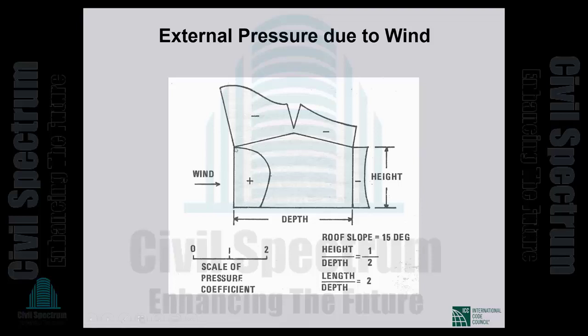And you see very clearly that with a gable roof, the suction here is the highest of any point on the surface of the building. This is a very basic problem in wind design. Because of that very high suction, the windward roof may be sucked up. Wind may suck it up, and when that happens, this wall loses lateral support, and then it doesn't take much for the wall to come down, and that's the end of the building.